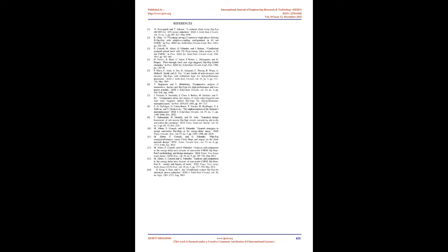In this work we introduce a new flip-flop structure, the double-pulsed set conditional reset flip-flop, DPSCRFF, which is up to 3 times faster than the fastest previously known flip-flops while consuming the same power as the lowest power flip-flops. The DPSCRFF is a single-ended static flip-flop design with a single logic stage which can include arbitrary logic functionality. The DPSCRFF is compatible with static or dynamic logic, and in particular can directly drive following dynamic logic.